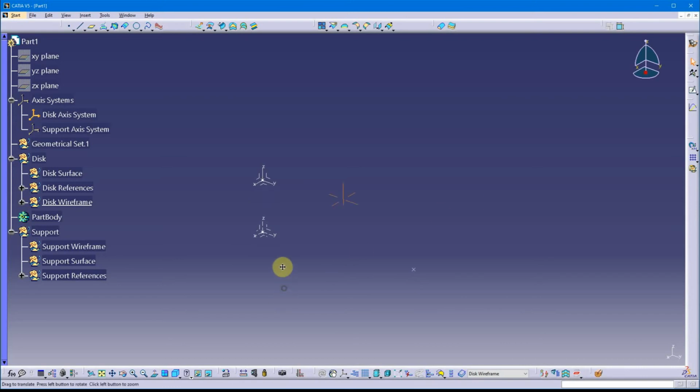So in this video, I wanted to show how I integrate surfaces with bodies inside of CATIA. So the first thing I'm going to cover here, the creation of surfaces. In this case, I'm going to have what I refer to as two Solidify groups, and that means I've got a collection of surfaces, reference elements, and wireframe elements that will lead to one particular surface that I will eventually solidify into a body.